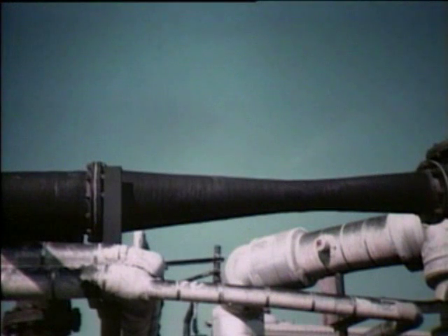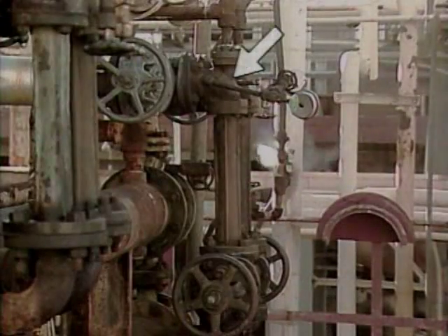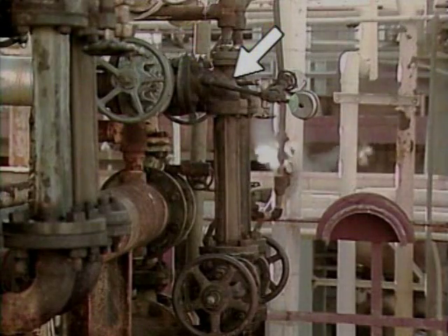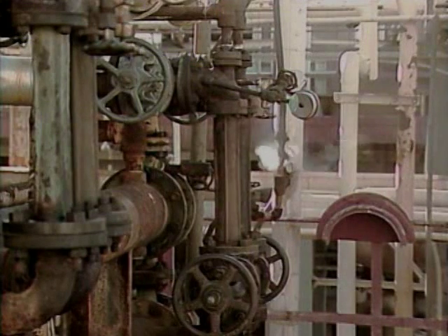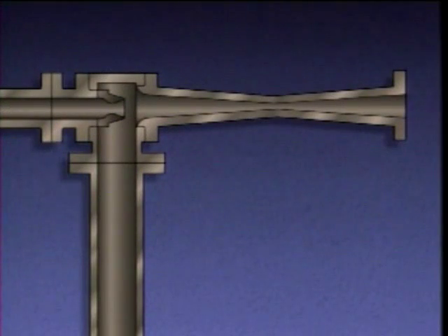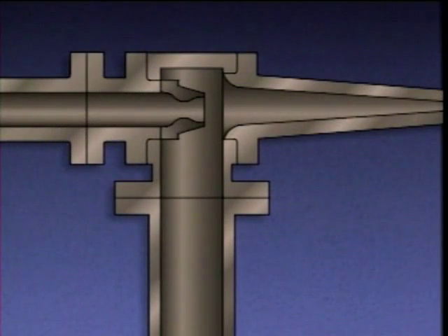Another component that's used in liquid as well as gas and vapor systems is a jet pump. A jet pump uses the flow of one fluid to move another fluid. An ejector that uses steam to remove air and other non-condensable gases from a condenser is one type of jet pump. There are no moving parts inside a jet pump. Instead, the pump relies on energy conversions to operate. The jet pump shown here has a nozzle, a pump inlet, a combining chamber, and a discharge section.